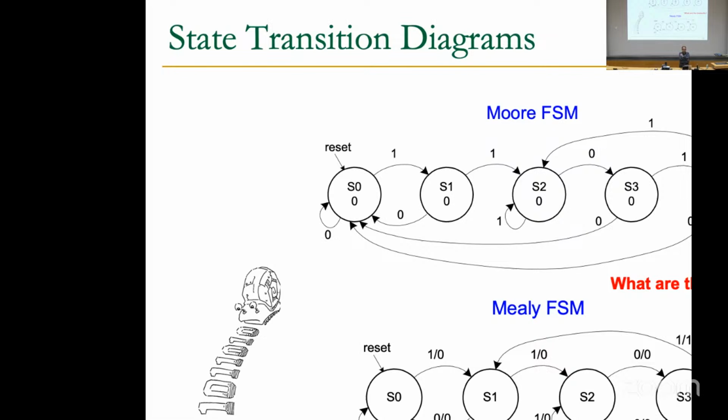But there is also another very important thing about Moore. You saw a kind of glitch in the previous lecture, right? Do you remember? There was an input with a glitch, a very short pulse. Usually in a Moore machine, your outputs are much more stable. That's very important because the output is defined by the state register, and state registers are stable because they are registers.